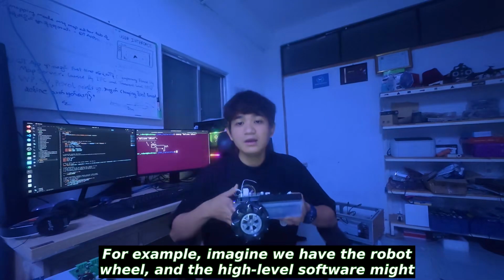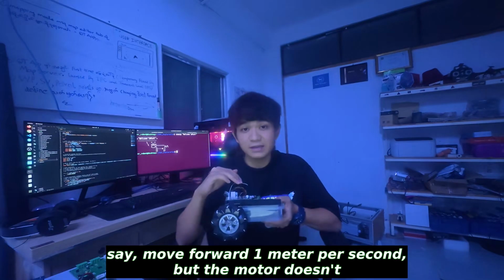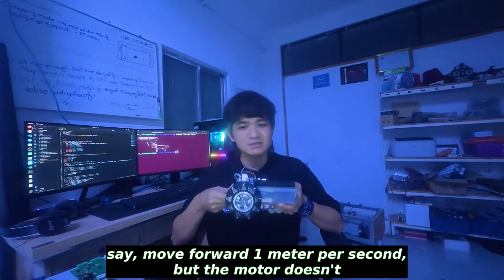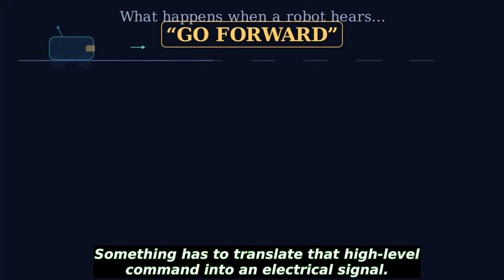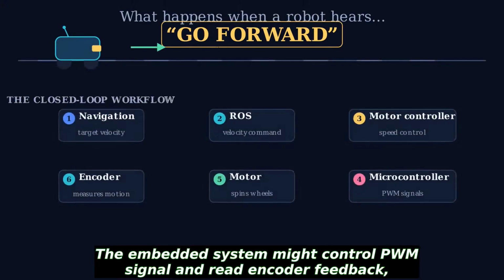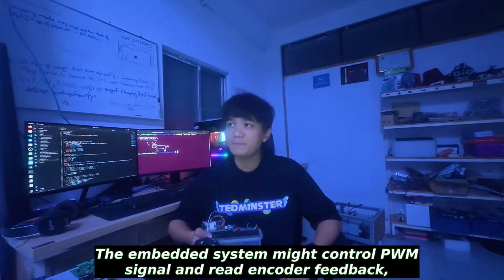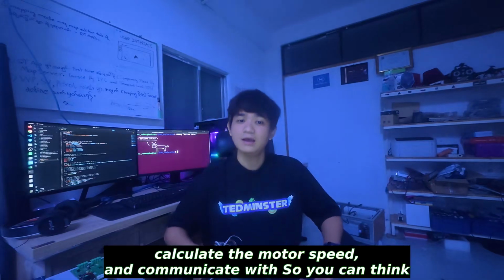For example, imagine we have a robot wheel. The high level software might say move forward 1 meter per second, but the motor doesn't understand the command directly. Something has to translate that high level command into electrical signals. The embedded system might control the PWM signal, read the encoder feedback, calculate the motor speed, and communicate with the main computer.